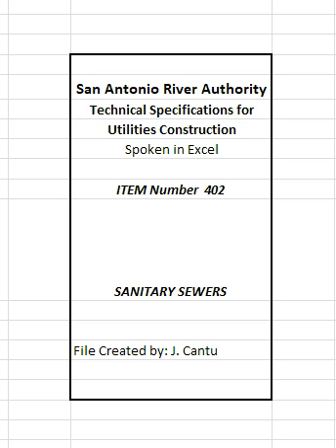All sanitary sewer mains shall be constructed in accordance with the specifications herein outlined and in conformity with the required lines, grades, and details shown on the plans and as directed by the engineer. Successful passage of the air test, as described under TCEQ criteria, shall be required for the acceptance of the mains. 1. Ductile iron pipe 24 inches and smaller shall rest on an undisturbed earth foundation where stable bedding conditions exist, continuously throughout its length, true to line and grade.